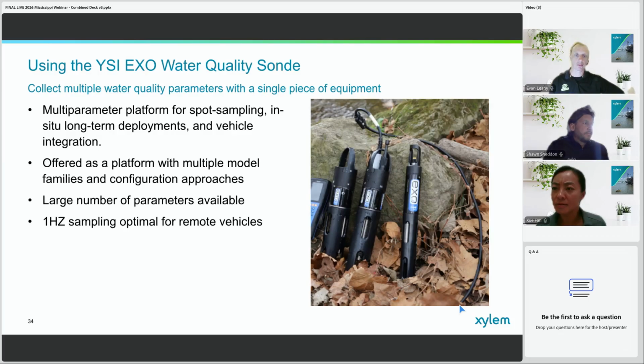Next, there's also another question, just briefly, on the SURF B batteries. There is one from Christoph Sauter about battery size. The 15 amp hour batteries will not fit. The maximum capacity of the SURF B is 12 amp hours or less. So we usually say between 6, 9 or 12 amp hour batteries, and it takes 2 batteries of the same capacity.